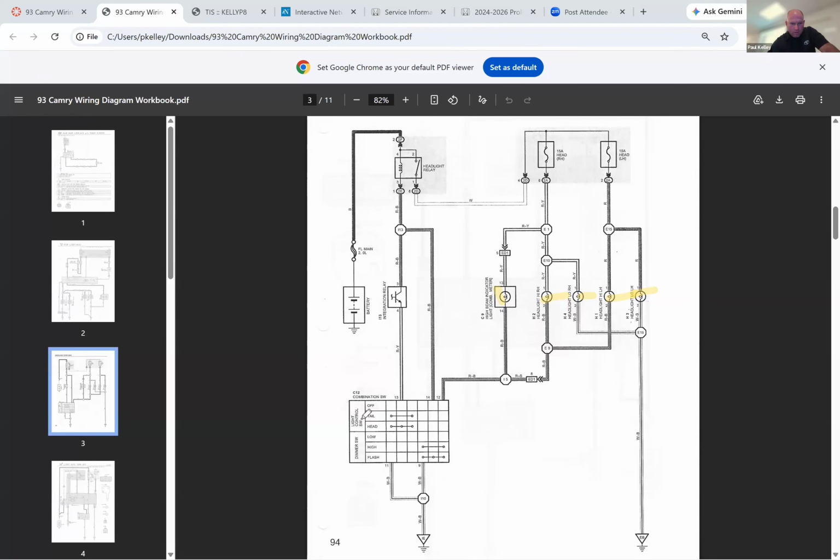Okay, so if I go to turn on the headlights, let's take a look at headlights. See this? Headlights right here. Now when I do that, understand 13 becomes connected and can go down to 11. Okay, that was some of the most important parts.